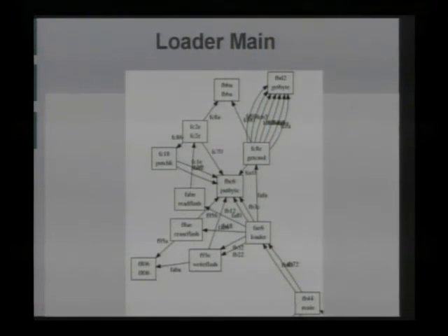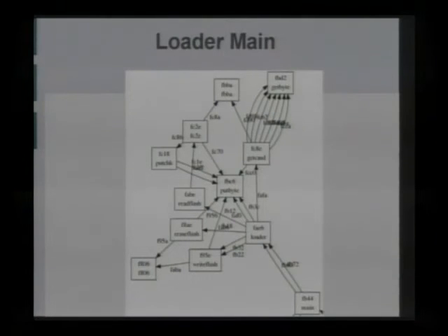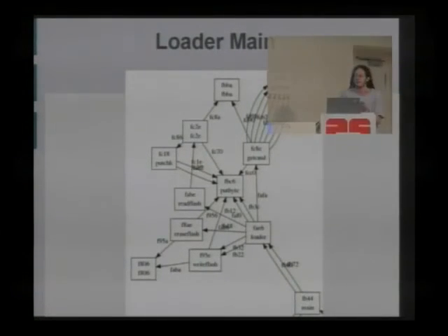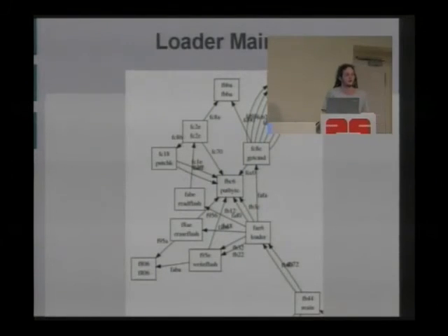And then this code here is used to fetch serial bytes. You've got get byte, which is called many times from the get command function. Put byte is when bytes are written over the serial port, and this is for a sort of wake-up initialization with the PC. So when you start GDB proxy, so that you can debug the target board, before the actual JTAG debugger software is run, this code is run, and it's here that updates are read into the device. So it quickly checks over the serial port to see if there's new firmware, and if there is, you can load it through.